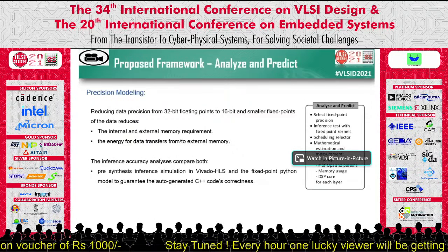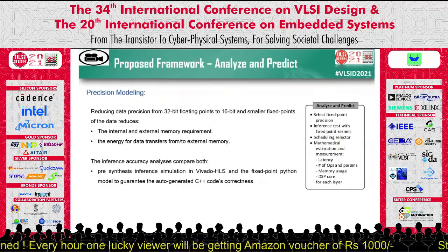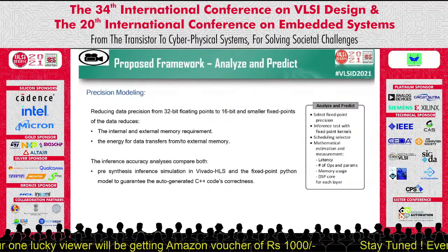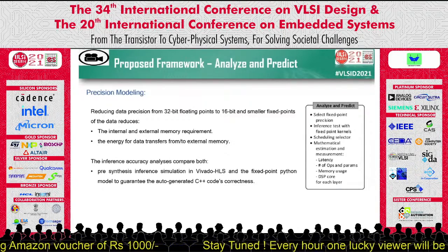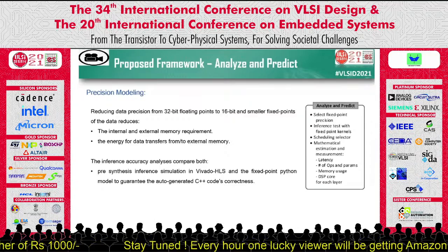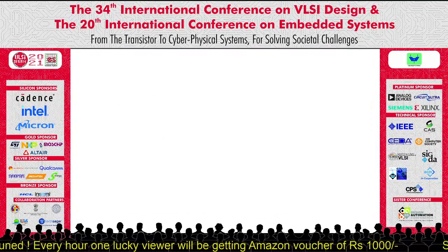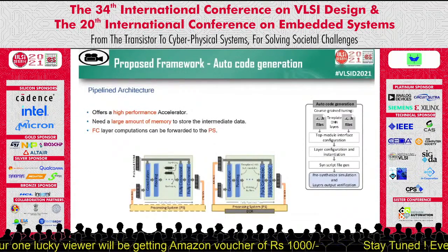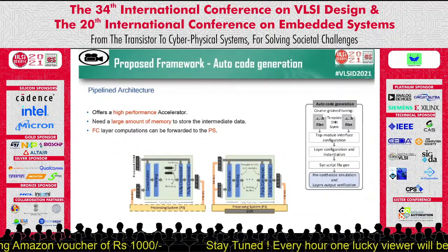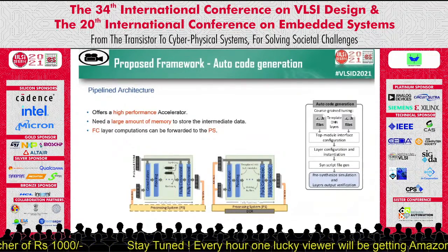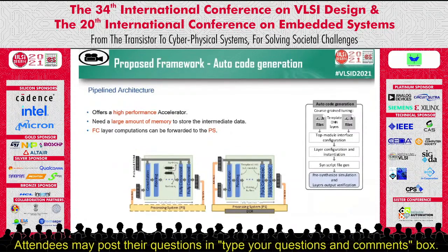The tool first uses arbitrary quantization to convert floating point kernels to fixed points, and then executes an inference accuracy analysis to ensure that the output is meeting their preference. This information, which is learned, assists the code generator to configure and set an appropriate hardware accelerator before running high-level synthesis. The computation within a DNN accelerator can be carried out using a pipeline or data flow architecture.